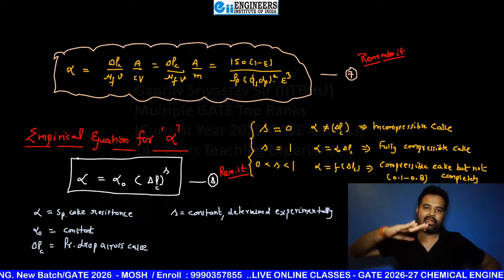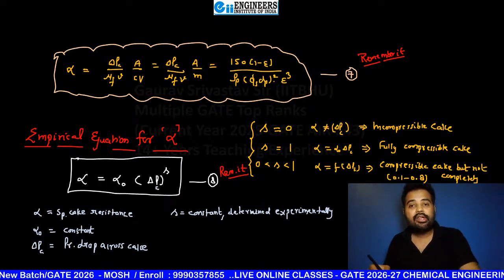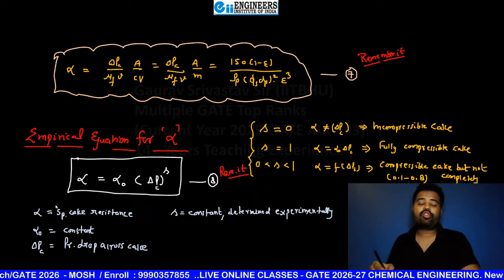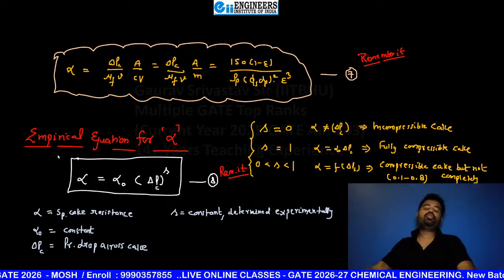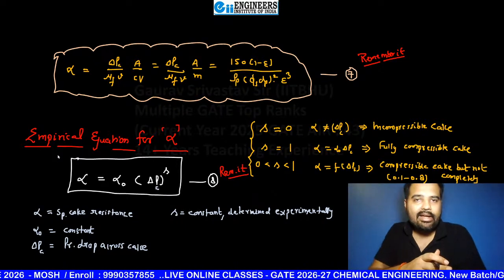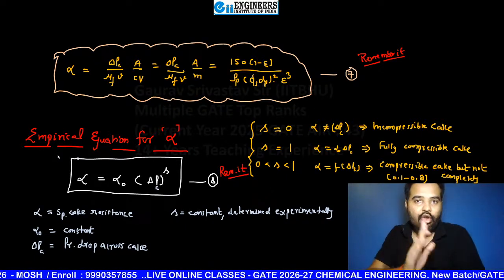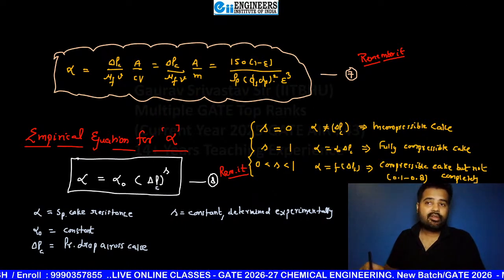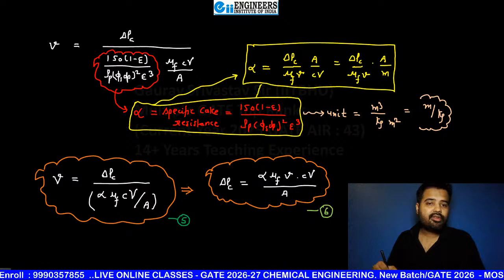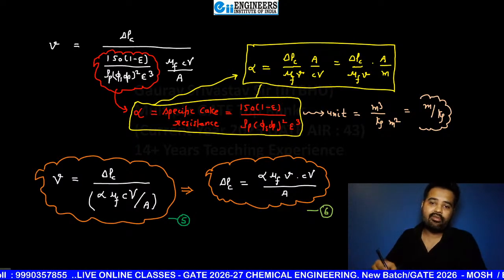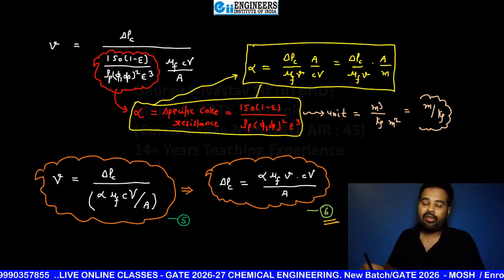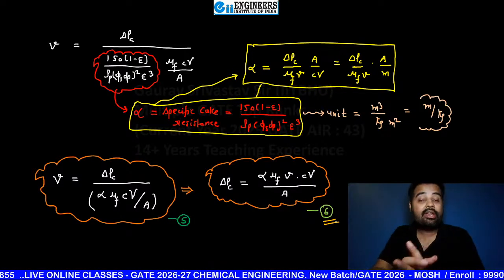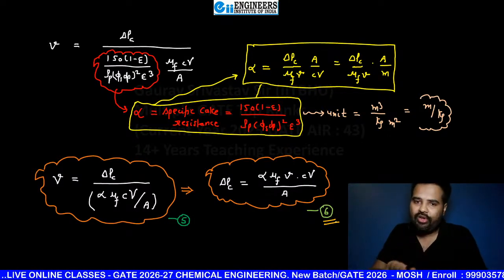That is the compressible cake here. Okay, so is everyone crystal clear in this topic till now? No doubts at all? So this is all about your first part, that was delta Pc, pressure drop across cake. And the equation you got, that you need to remember, is most important for the next derivation. This is equation number 6. When I write delta Pc plus delta Pm is equal to delta P, we calculate the overall pressure drop here. So the first part is completed.